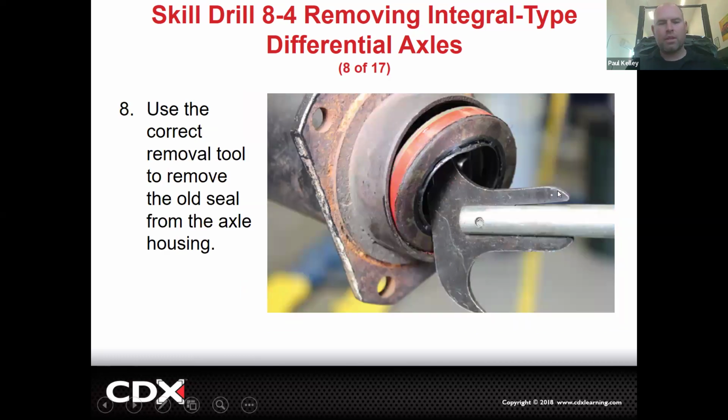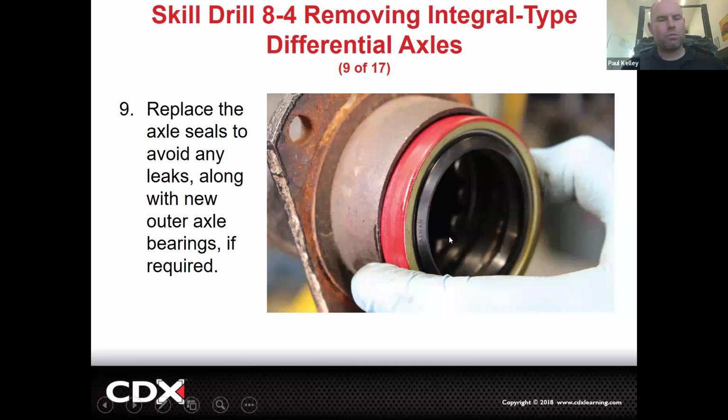Cool. So we can slide it out. Now you can see you can get at this axle seal. That's how you do the seal. And behind the seal, there's a bearing. So you see the little bit of this roller right here. So if you had to do axle bearings, you got to pull the seal first, then you got to put a slide hammer in and pull the axle bearing. And the axle bearings would have all the same symptoms as a wheel bearing. So if it's the right side axle bearing and you go around a left turn, that right side axle bearing gets more weight on it, and that would make the noise. Assuming it's one of these semi-float or non-floating. If it's a full-blown floating axle, it wouldn't really be an axle bearing. It would be those actual big hub bearings out there.